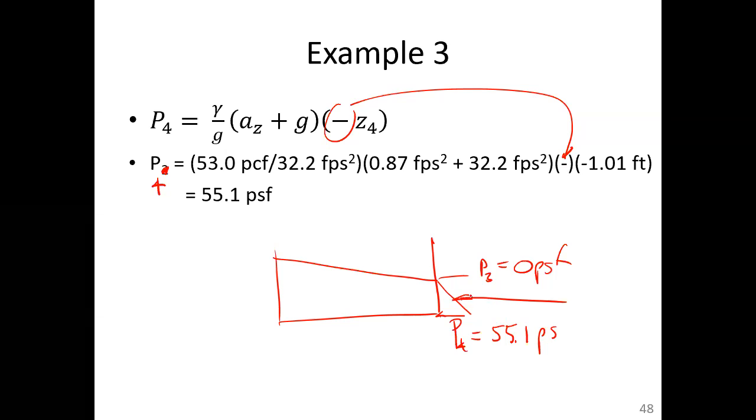And what we can then do, we can then take that linear pressure distribution, calculate the pressure at the center of area, and then with that pressure at the center of area, multiply it by the submerged area to get the force.